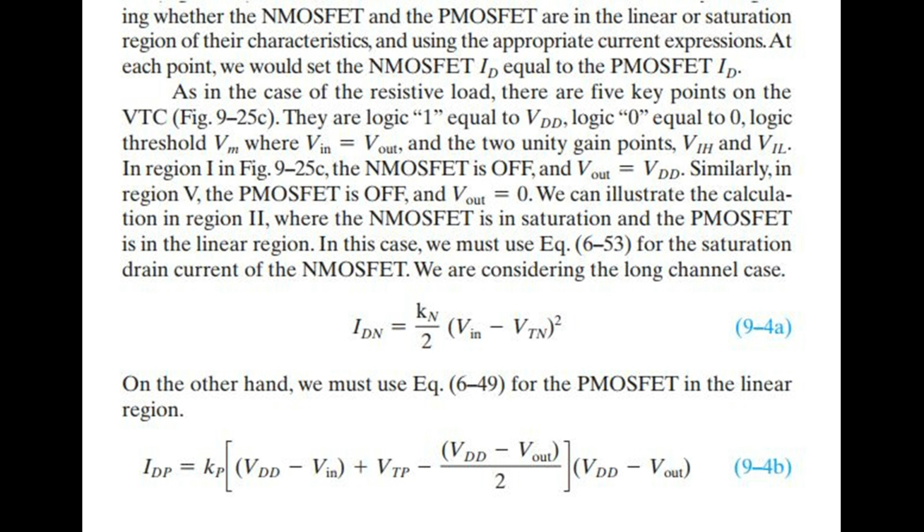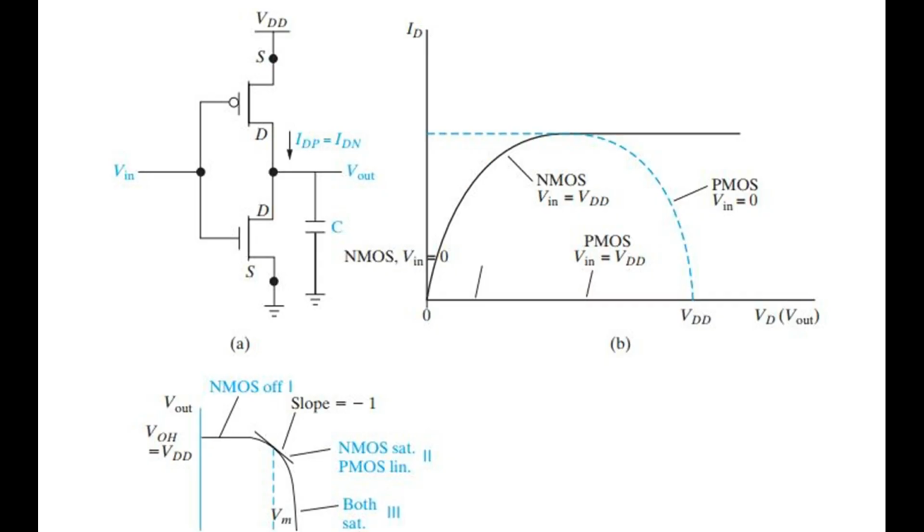Figure 9.25 Complementary metal oxide semiconductor inverter voltage transfer characteristics. A, N-channel MOSFET with P-channel MOSFET load and load parasitic capacitance, C. B, Determination of VTC by superimposing load line, output characteristics of P-channel MOSFET shown as dotted line, on N-channel MOSFET output characteristics.